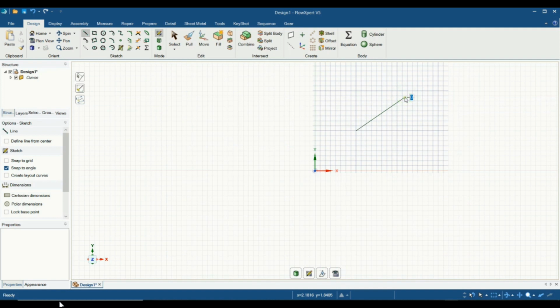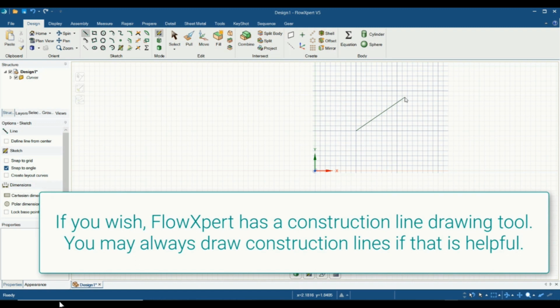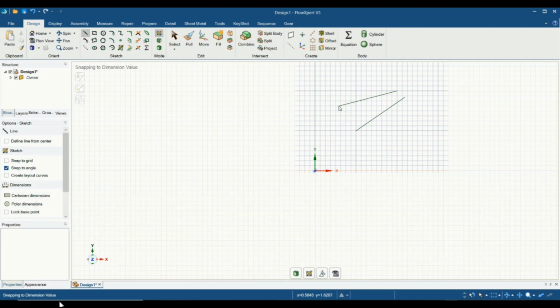This construction trick works for many of the tools. Note that any identifiable location can be used as the starting point. For example, we can use the same construction technique at the end of a line. Snap to the endpoint of the line and press the Shift key. With this technique, features may be drawn in precise relationships.